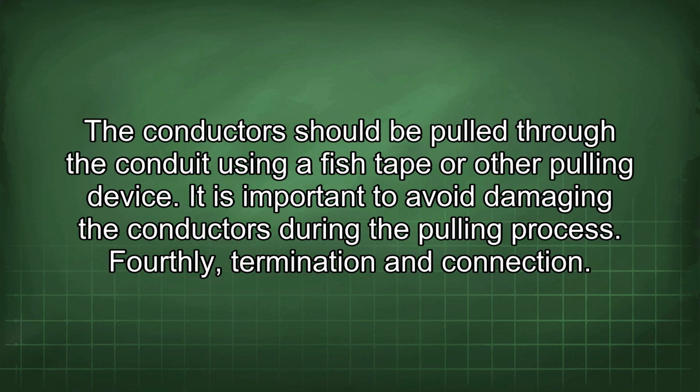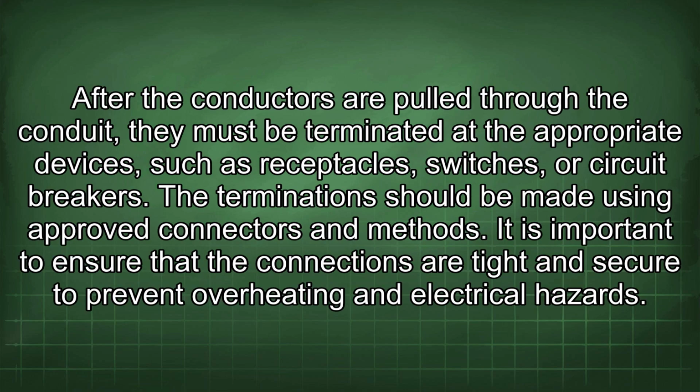Fourthly, termination and connection. After the conductors are pulled through the conduit, they must be terminated at the appropriate devices, such as receptacles, switches, or circuit breakers. The termination should be made using approved connectors and methods. It is important to ensure that the connections are tight and secure to prevent overheating and electrical hazards.